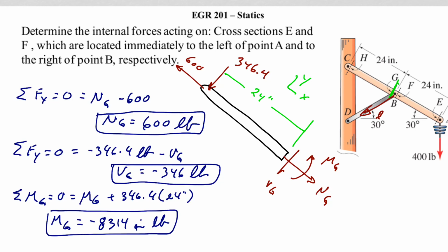You'll also note that I was very deliberate in making sure that the direction of these forces are opposite the direction of the cut from the previous side, so everything balances out and everything is in equilibrium internally to this system. I then summed forces in the x direction, which is a very simple one for this case, and then summed forces in the y, and then did our moment at that location. And you'll see that I got the exact same answer. So either method is fine when doing that, taking either free body diagram. We should get the same results, and we do.